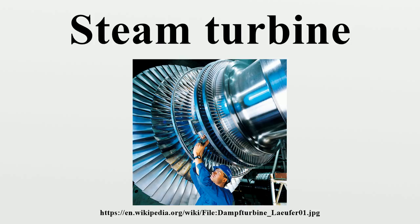By 1905, when steam turbines were coming into use on fast ships and in land-based power applications, this was more efficient with high-pressure steam due to reduced leakage between the turbine rotor and the casing. This is illustrated in the drawing of the German 1905 AEG marine steam turbine. The steam from the boilers enters from the right at high pressure through a throttle, controlled manually by an operator. It passes through 5 Curtis wheels and numerous reaction stages before exiting at low pressure, almost certainly to a condenser.